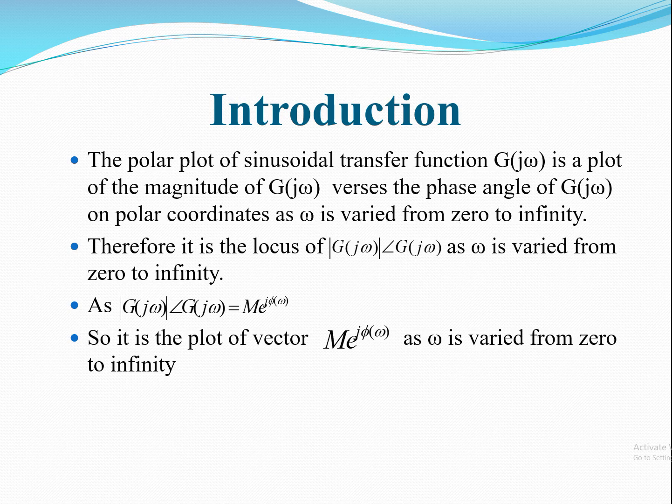So we will have an x-axis and a y-axis. Magnitude versus phase angle, so your y-axis will be the magnitude and the phase angle of G(j omega) H(j omega) will be the x-axis. Generally H(j omega) is taken as unity feedback, so we have not written it here, so ultimately you have G(j omega) into H(j omega), while omega is varied from 0 to infinity.